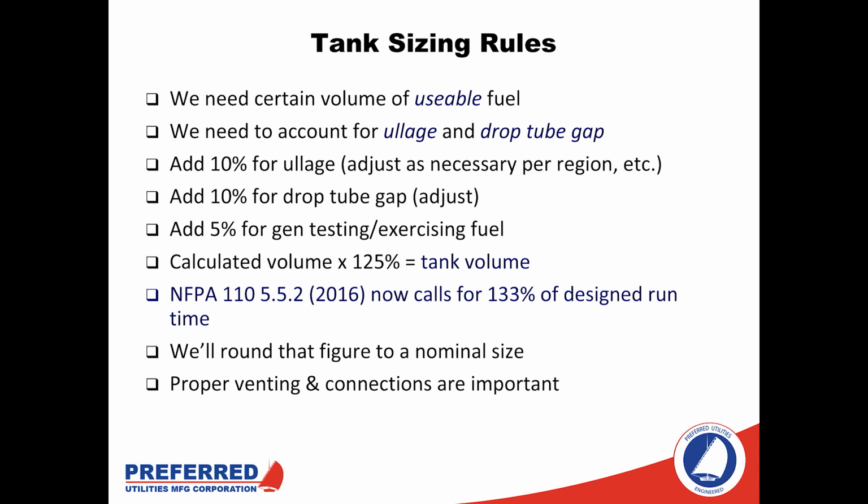So that would come up with, let's say, 125% of that raw number. Now, NFPA in 2016 now calls for 133% of design runtime to account for testing, so we would bump that number up to 133% of that raw number. And we'll round that figure to a nominal size, and that would be what we would base our bulk storage